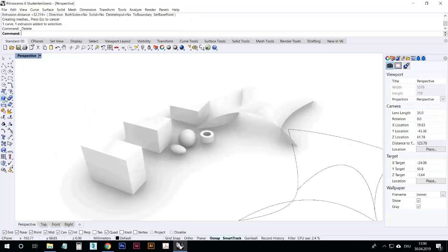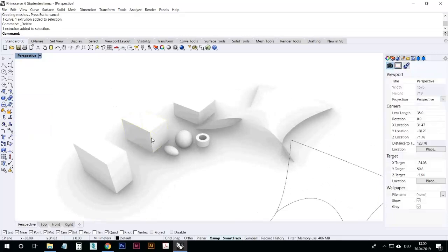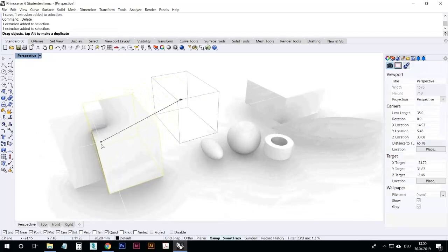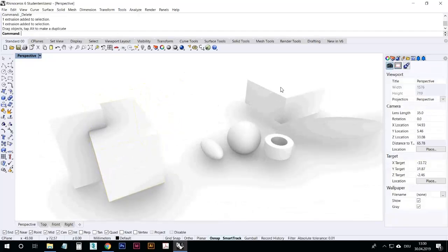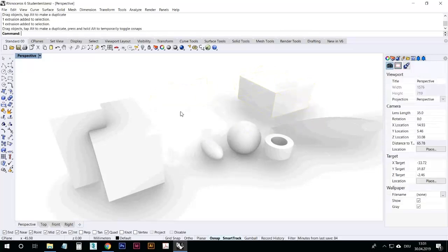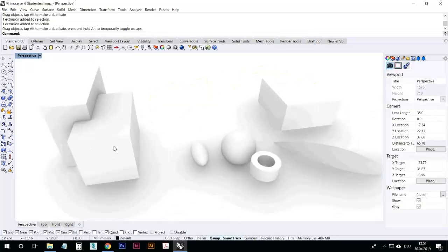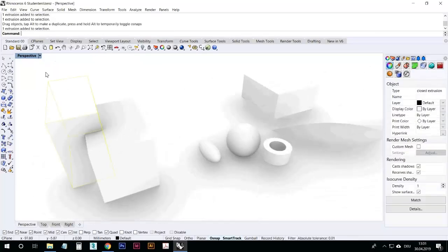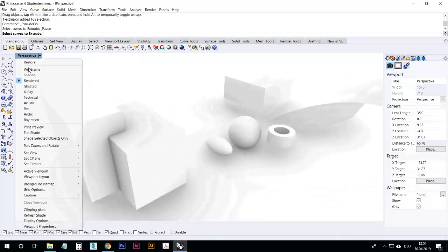If we go further, we have something called Boolean union, which is very useful. So if I want to join these two into one solid shape, they have to, of course, touch each other, right? So I can move that into that one like this. You see that if I just select something and pull, I can actually move things. I don't have to move the whole time, but when you type move or select the icon, it's much more exact, of course.